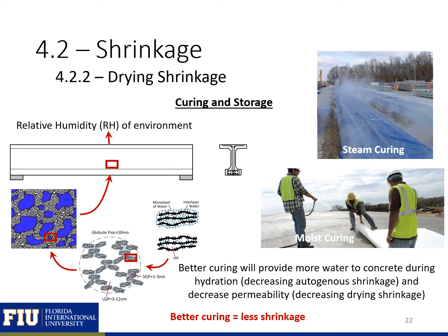Next, we'll see how our curing and our storage can affect our drying shrinkage. Remember that our shrinkage is mainly caused by water movement, so the desire for water to leave the beam to the environment, or to be used within the member itself to hydrate the concrete. If you apply an external source of water, it's going to discourage the water in the larger pores from leaving, which will discourage water in even the smaller pores from leaving. So this means there will be less water movement.